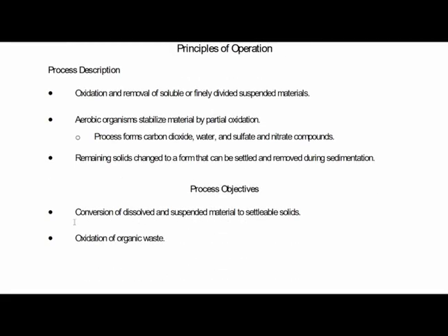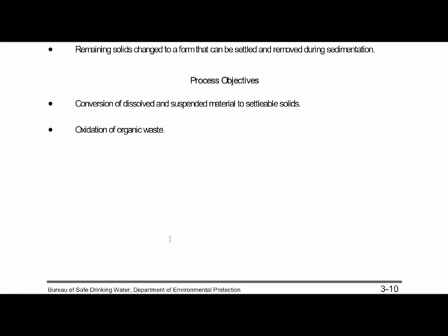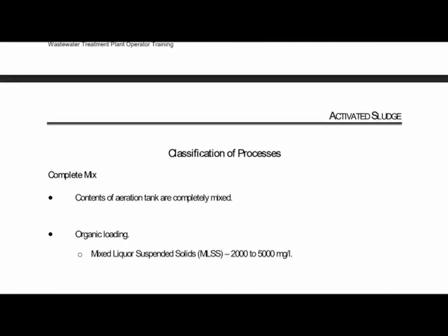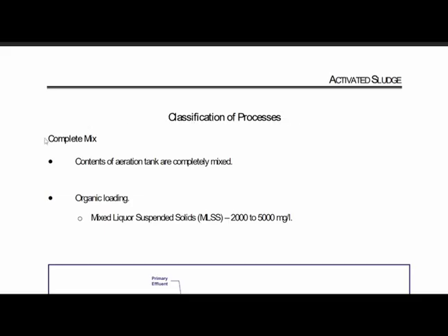Process objectives. Conversion of dissolved and suspended material to settleable solids. Oxidation of organic waste. Classification process. Complete mix. The contents of the aeration tank are completely mixed. Organic loading: mixed liquor suspended solids, or MLSS, is between 2,000 to 5,000 milligrams per liter.